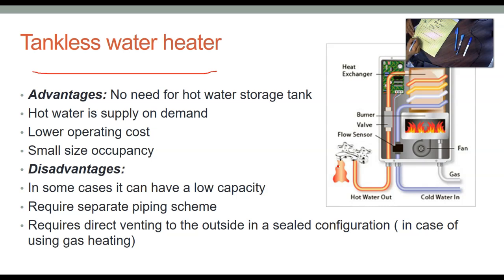Let's say you have a 3-story house and this is your boiler and the faucet is in here. This is the sink, and you have your faucet over here and you want some water. You open the water, so all the water coming from the pipe all the way to here has to clear out, and probably we have here at 140, and probably here it's going to be 60, 70, and so you have to pull all this water which is wasted until you get the right temperature water. So this actually cuts that distance and saves you a lot of energy.